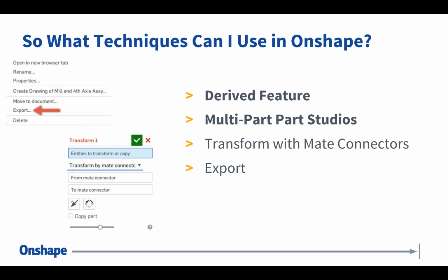And one of the biggest advantages to the modeling techniques I'm getting ready to show you is, if I build multiple parts together and then I decide to change that original part that I'm making, the fixtures would update, assuming I've designed it with the correct design intent. So not only do we have the ability to do that, but we have the ability to make it really intelligent. I'm going to show you what I mean in just a second. But yes, you can design the fixture and the product concurrently, and they will update.